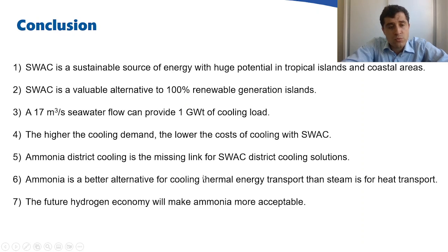The conclusion is that SWAC is a suitable source of energy with huge potential in tropical islands and coastal areas. SWAC is a valuable alternative to 100% renewable generation islands. A 17 cubic meters per second seawater flow can provide 1 gigawatt of thermal energy of cooling load.